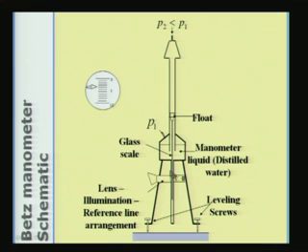The height of the meniscus is measured by having a floating scale. The scale goes up and down, and the marks on the scale correspond to the main scale division, and the other one is the vernier, which is projected by the optical arrangement, and therefore we measure the two in this form.